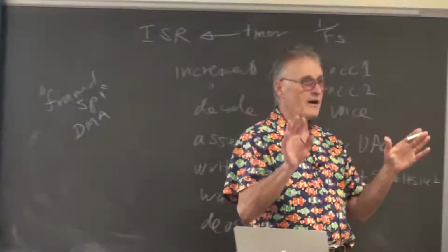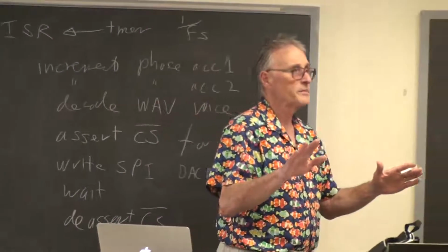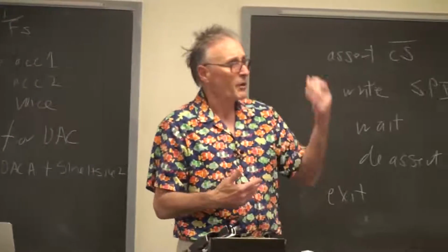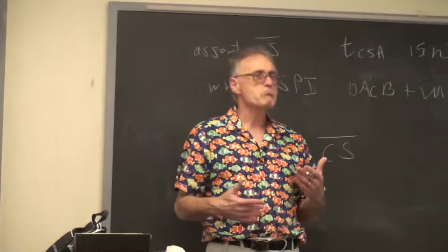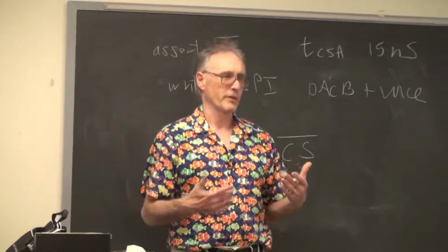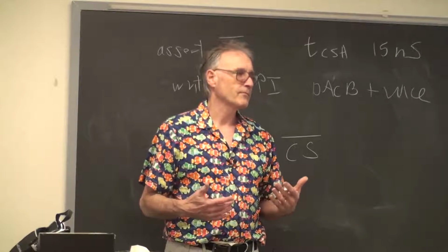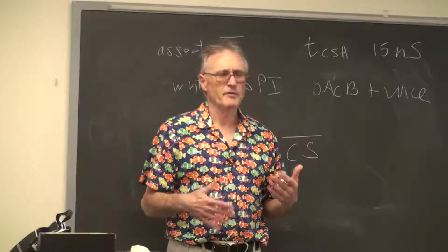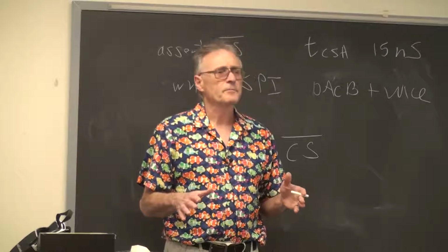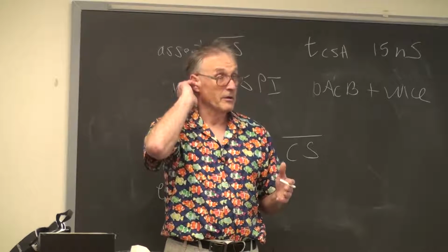So you can have the two conversations going at the same time. The CPU can run at full speed, the DMA can barf out stuff at full speed, and they do not slow each other down. You've just doubled your bandwidth. For some things that can be very good. For this, it's not so necessary. In fact, it's not necessary, although it's kind of entertaining.